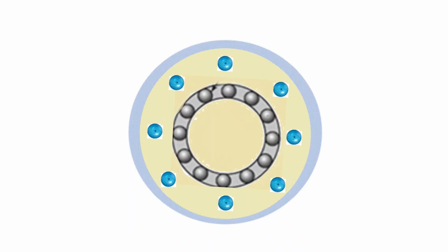So as we know, this is the stator where the windings are placed, and that is excited by the three-phase supply. Flux is produced from the three-phase supply, and the resultant flux of the three phases will be revolving over the air gap.